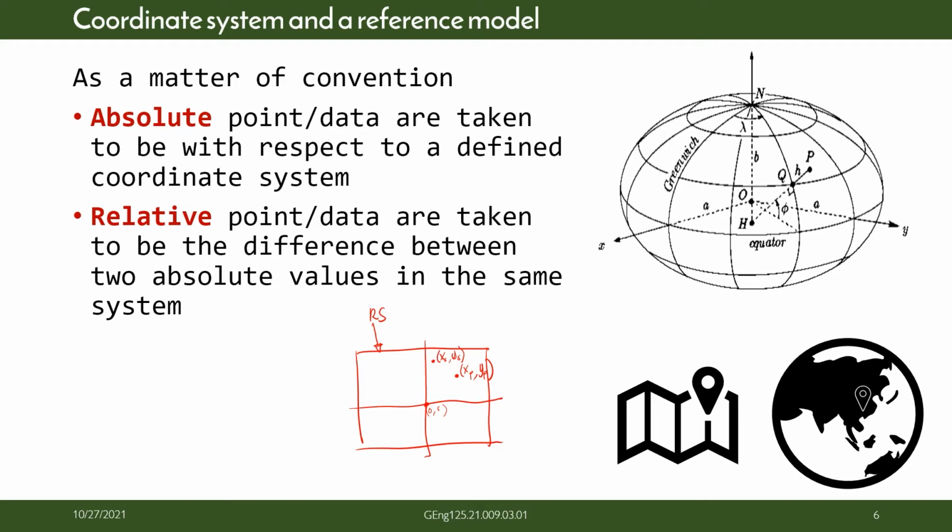When we establish new corners or conduct a survey, we always refer our survey from a known reference position or reference ground control point, or GCP, which is attached or defined from a certain coordinate system.